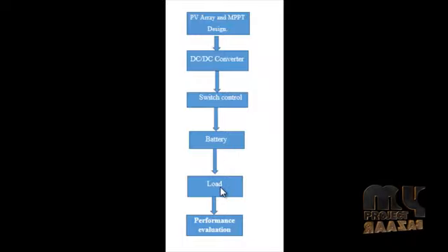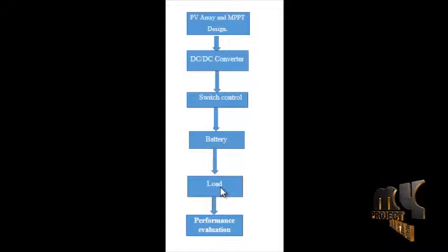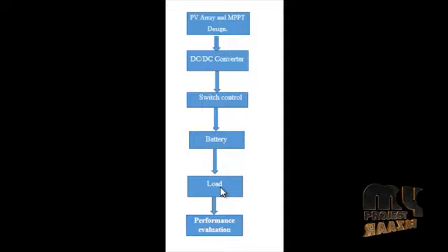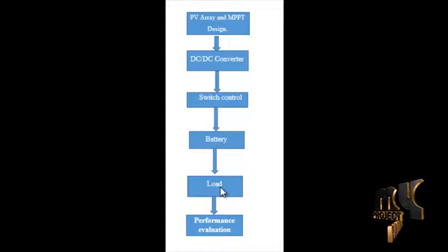The next block is load. To begin with, a single resistor was used to represent the load. Its resistance is found by assuming it to be a 4000 watt-hour per day load at 12 volts and keeping the load constant over a full day of 24 hours; the resistance can be found to be 8.64 ohms. Keeping the load constant is simple in principle, but to vary the current usage throughout the day, it can be modeled with several varying resistors and accompanying switches that turn on and off at predetermined times.